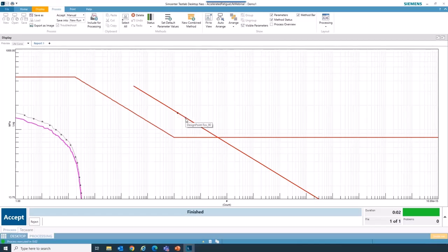Here there is a certain number of cycles, and then as we increase the load by 15%, the number of cycles reduce significantly as shown here. And if you continue to increase the load, maybe you can go up till here. It still has a linear shape to it. So that is a good information to know.